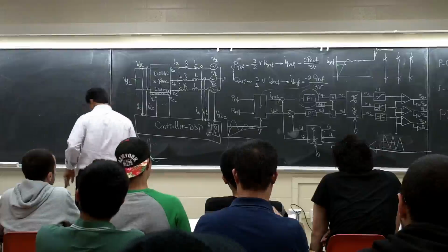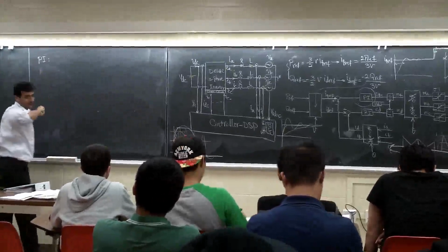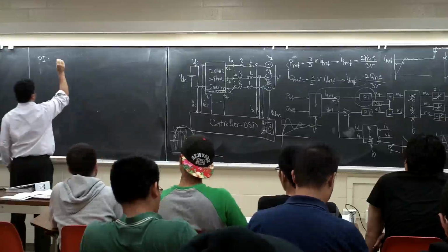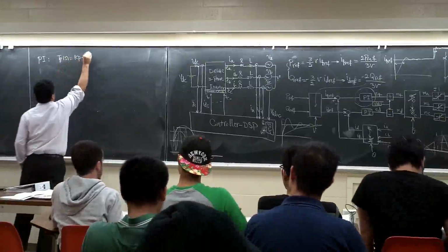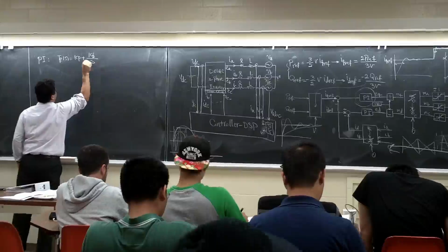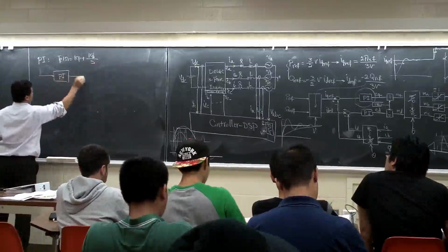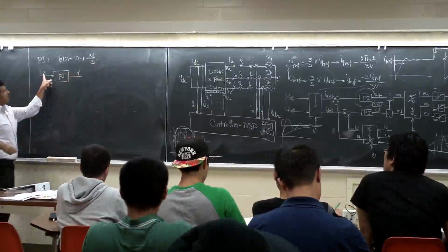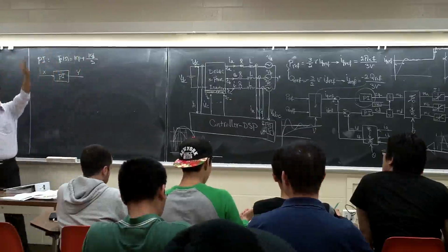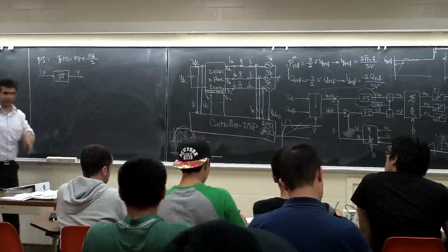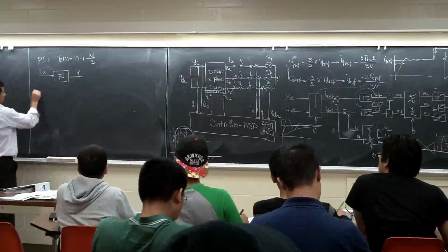Now, the type of PI. So what is PI? Basically, the transfer function for this PI is KP plus KI over S, right? You have a signal X coming, goes to the PI, and gives Y. Basically, it multiplies X by this PI. There is another formula for the PI. PSIM uses that one, and I like it better.